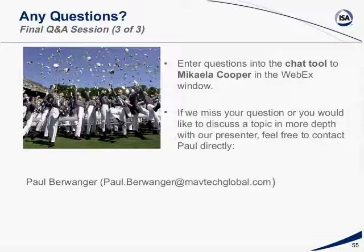No, it is not a warning for them. This alarm system is for the operators, for operating that facility. It is not for process engineering. And so you want the facilitator to really draw that line. And we call that out in the alarm philosophy: it is not for the process engineer to use the system for their warnings. This is an operations and operator-centric system.